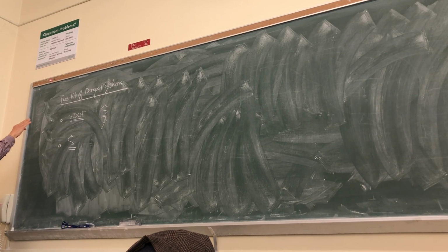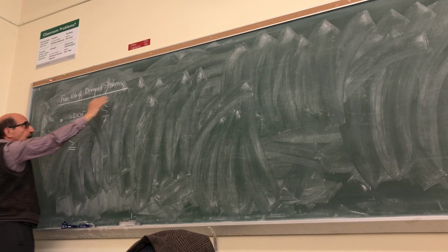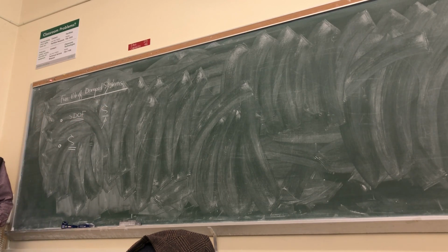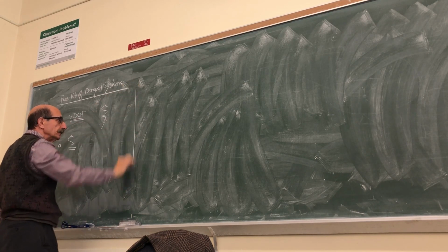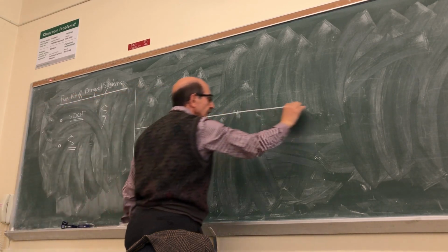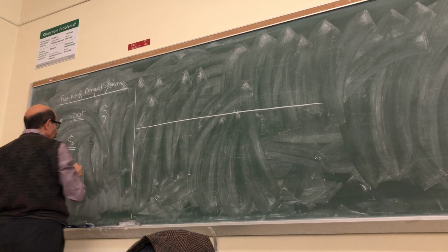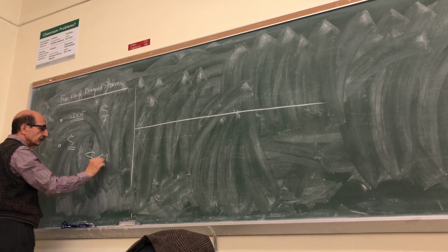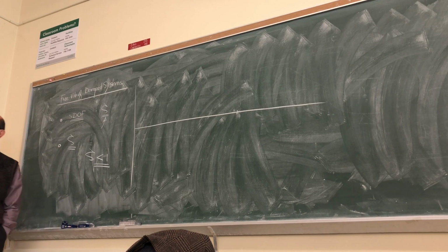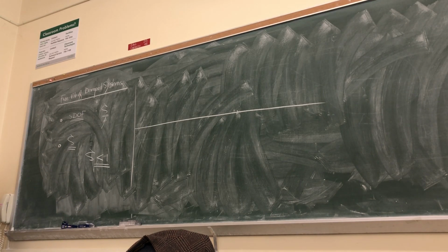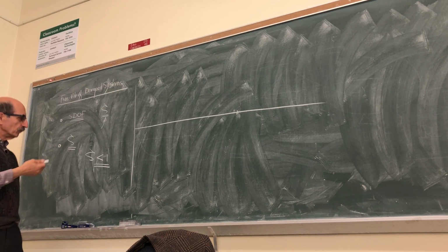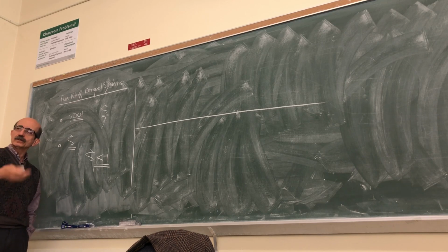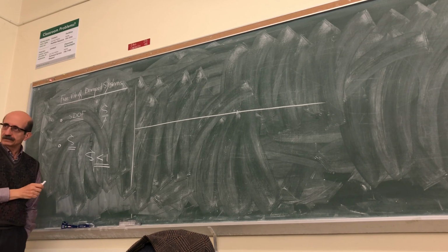So if you have a free vibration response of a damped system, one way to measure the damping ratio is from that response, especially for those cases that the system is underdamped, which is a vast majority of mechanical or structural or aerospace or marine structures, any structure. Most of the structures, even human body organs, whatnot, they're all mostly underdamped.